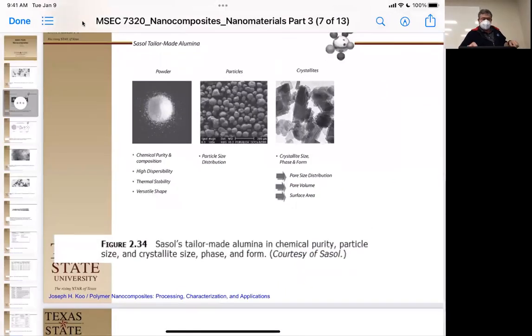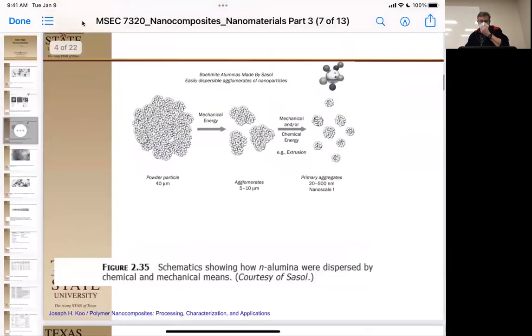Most of the time, we can't really get them from macroscopic to nanoscopic mechanically. We can, through cryo grinding or other ways, go from our macroscopic particles down to small conglomerates. Then technically you need some other process that will take it down. So typically you would use something more along the lines of, not cryo grinding, sonication or something that will break them apart again. Because what we're trying to do is break the energy between the little substrates and whatever the matrix is.